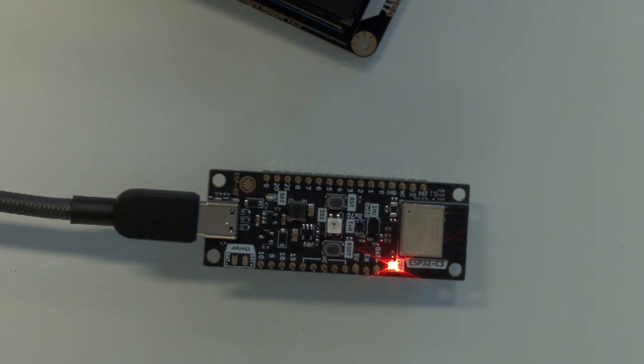Let's see what happens if I change this to a much lower duty cycle. Maybe I'll change it to a 10% duty cycle. So I just decreased the threshold value quite a bit, and now it's reflashing. Memorize what that brightness was ahead of time. Let's see, hopefully this is going to be dimmer now. Okay, it's almost done. Does that look dimmer? It looks a little bit dimmer.